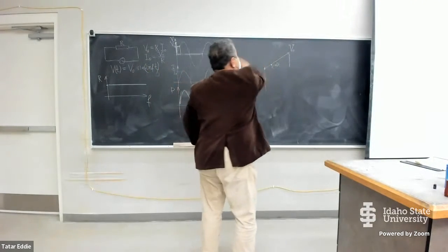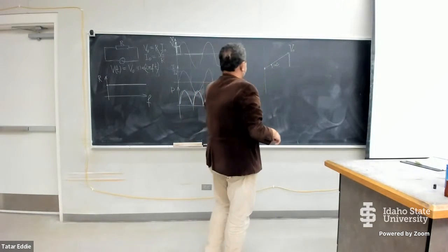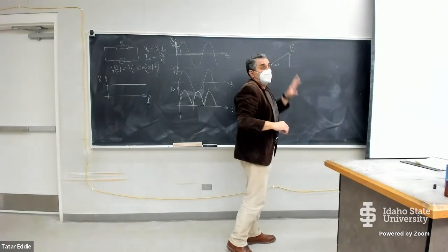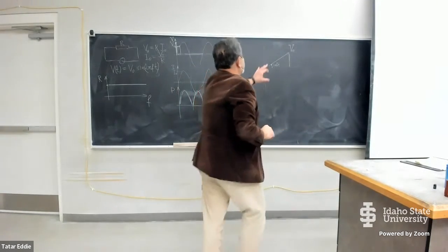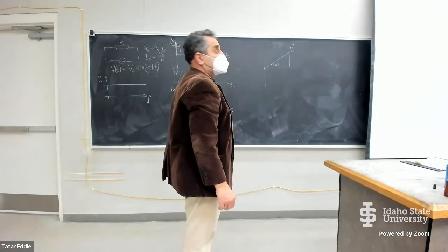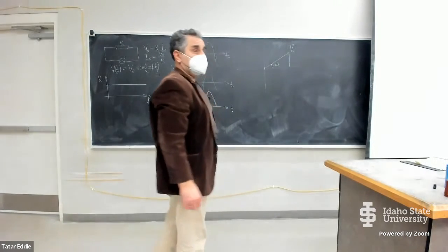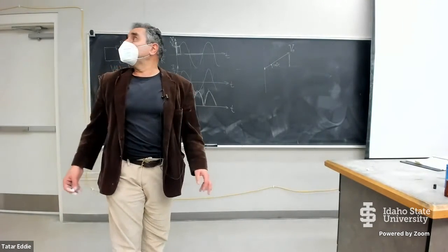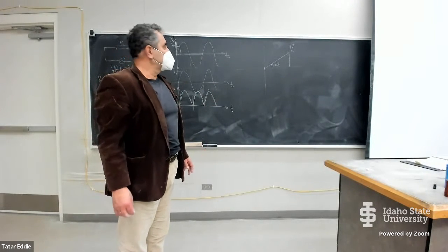So this phasor is constantly spinning, and at any moment of time, you can figure out the value of the voltage provided by the generator just by looking at the sine of this angle times V naught, the hypotenuse. So this is the phasor notation and the phasor way of thinking, similar to vectors, but with some twists.